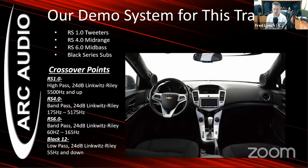I usually do always recommend, if you are trying to get a very well-staging vehicle, to underlap those crossover points a little bit, so you don't get frequency gain between the drivers that would ultimately cause smearing. And the RS 6.0s are crossed over from 60 hertz up to 165. And the Black 12, in this case, still 24 dB Linkwitz Riley for now, and is crossed over at 55 hertz and down.